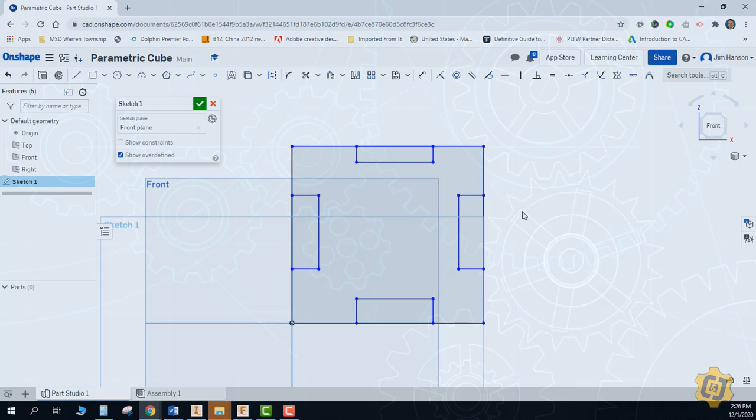But I could have done that as I drew. So if I had just deleted those, when I drew them, I could have done the same thing. I could have linked it onto there. I've not clicked. I've not actually grabbed it. I've just taught Onshape that that's something that I would like these 2 points to be in line with each other. And then I can do the same thing with this one. I just highlight it. I teach it that that's a reference point that it can tether to, and it'll do it for me. So you can do them afterwards, or you can kind of do them on the fly as